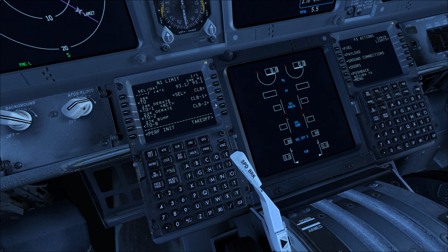So we're going to use takeoff 1 and climb, and we used a 36. Put that in there, and then just change that back because it moved it automatically. Takeoff page, flap 5. Double click CG. That's our trim for takeoff, 4.92. That's when we trim the aircraft.